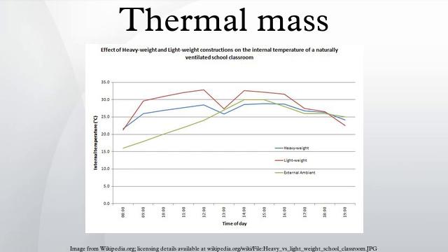Earth, mud and sod. Dirt's heat capacity depends on its density, moisture content, particle shape, temperature, and composition. Early settlers to Nebraska built houses with thick walls made of dirt and sod because wood, stone, and other building materials were scarce. The extreme thickness of the walls provided some insulation, but mainly served as thermal mass, absorbing thermal energy during the day and releasing it during the night.